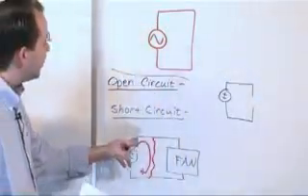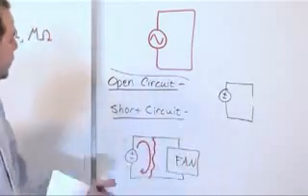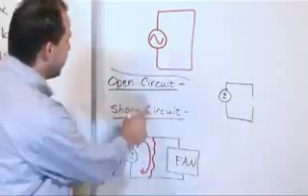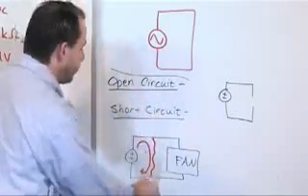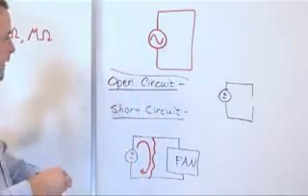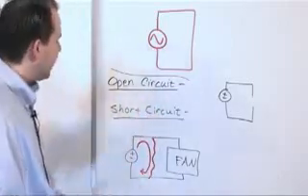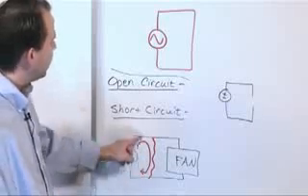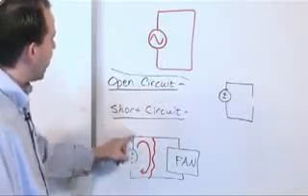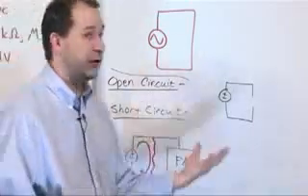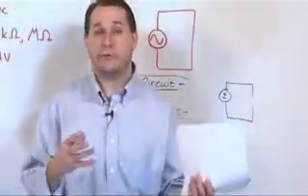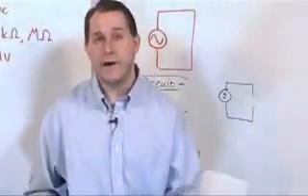So because of that, the electricity never even gets to the fan. That's called a short circuit. It's called short because it truncates, or shortens off, the circuit. And it's very bad for lots of reasons, because whenever you get current going through a wire with no resistance or very low resistance, you can generate a lot of heat, and you can actually cause a fire.